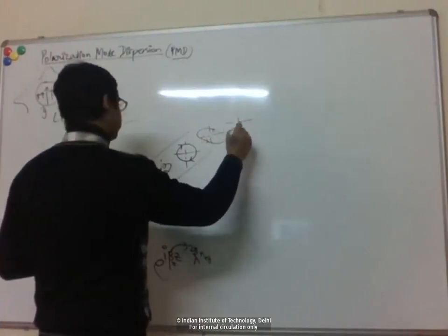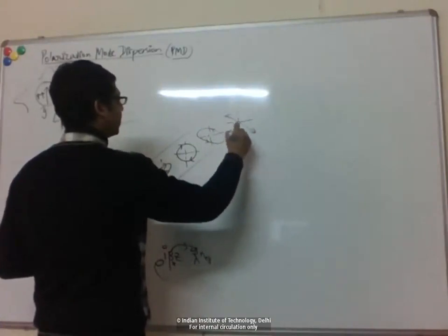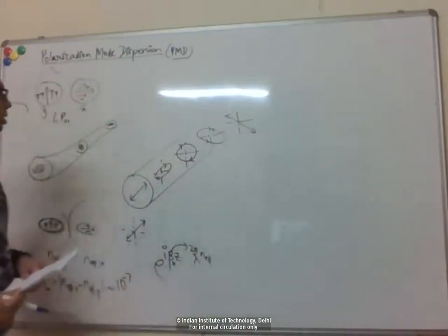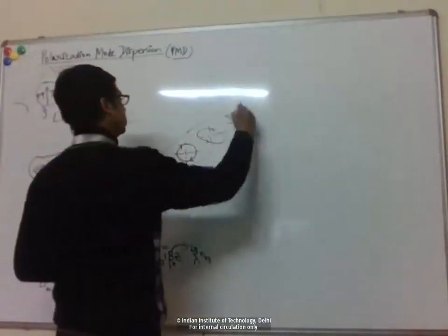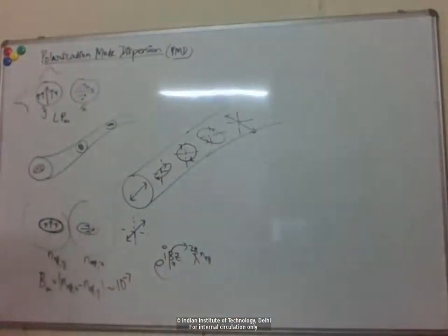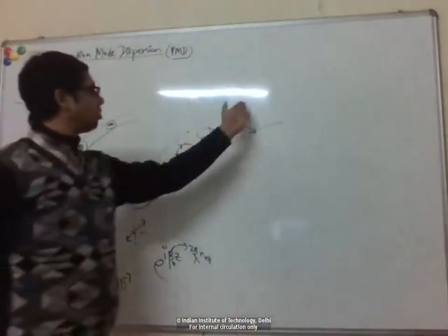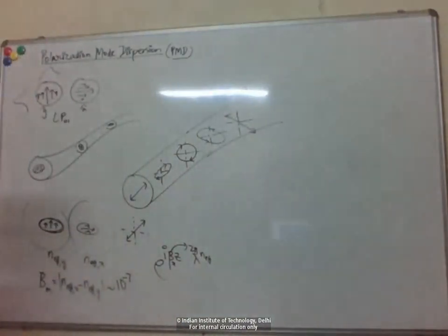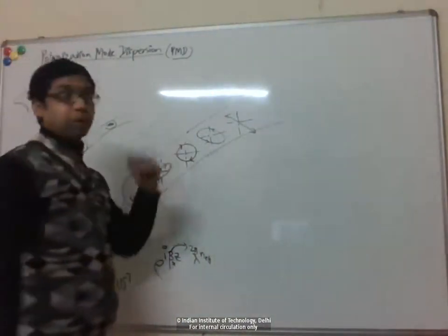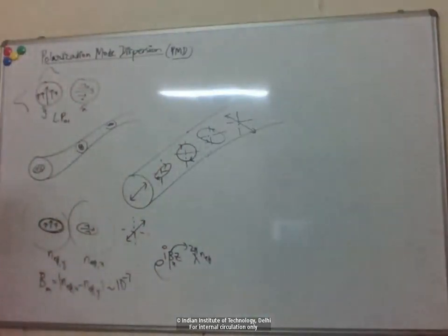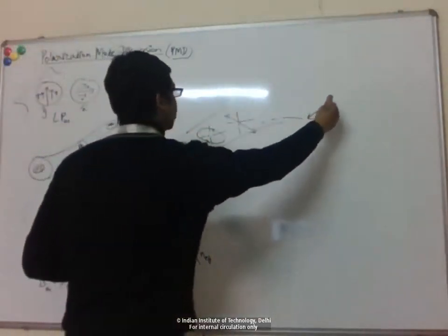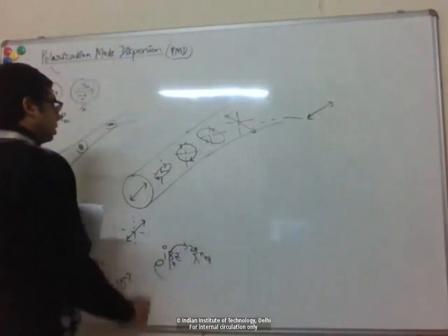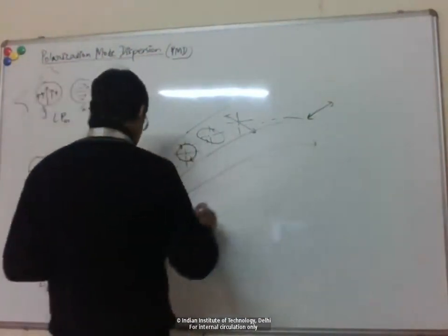And then when the phase difference becomes pi, it will become diagonal in the other direction, right? So basically, the polarization will evolve as the mode is propagated, right? Due to the birefringence, right? So after some point, it will go through the entire cycle and come back to its original polarization, right? So this length is known as the beat length.